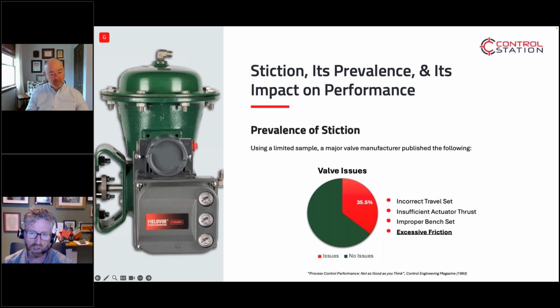It's about trying to differentiate between those undersized, oversized, incorrect travels, so that you're diagnosing them as early as possible to find the causes. It's very hard to change an oversized or an undersized valve. It's not something you just whip out and put a new valve in. You may have to live with it, but understanding what it's doing and understanding the limitations will then feed into that.